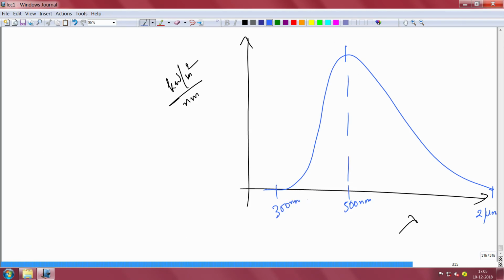So the thing is, whatever semiconductor you use, and of course predominantly we use silicon because silicon is very cheap. Silicon is integrable to all CMOS, all electronics is silicon based mostly. So if you make something in silicon, it is easy to integrate, easy to scale up, easy to commercialize on a large scale. If you make a very exotic perovskite solar cell, then large scale manufacturability and integration into the industry become tricky. So there is always a cost aspect, and silicon always wins in the cost aspect. So if silicon works as a solar cell, we will use silicon.